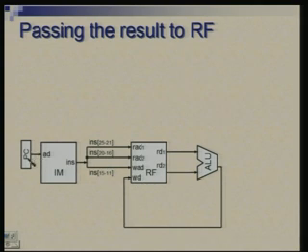So, basically starting with PC, we have a sequential element here. Okay. So, at edge of a clock, a new value is available at the output of PC, okay, which defines address of a new instruction, and as a function of that we get the instruction, as a function of that we get the operand, as a function of that we get the result, and finally result is available at the input of register file. So, now at this point when a clock edge comes to register file, this information will get stored at that instant. So, we are assuming that transition in the state of register file would be edge triggered.